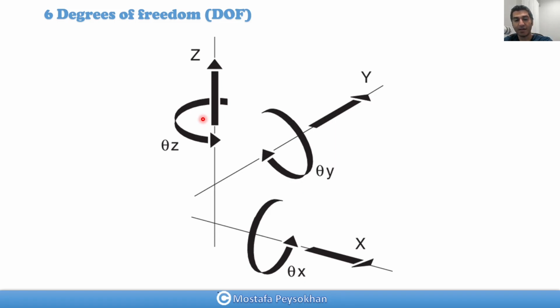For a lens system, which is usually axisymmetric along the optical axis, we have a name for each degree of freedom that needs to be constrained. Or when we want to see the effect of tolerancing on each parameter, we usually say, for example, what is the effect of decentering a lens element. Now I'm going to talk about the naming convention that we use for an individual lens element, which in future will help us to understand the requirements for an optical system in a better form.